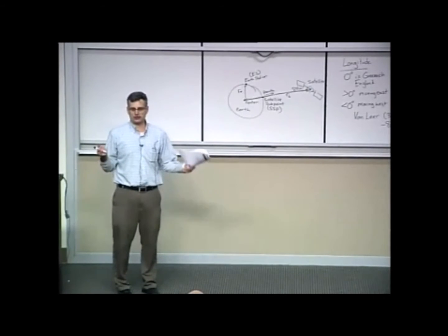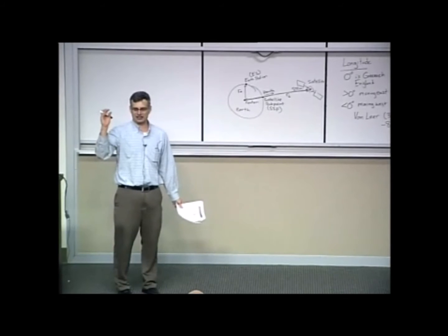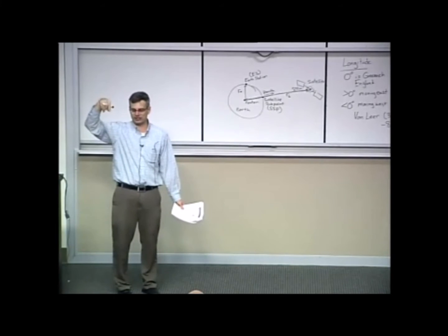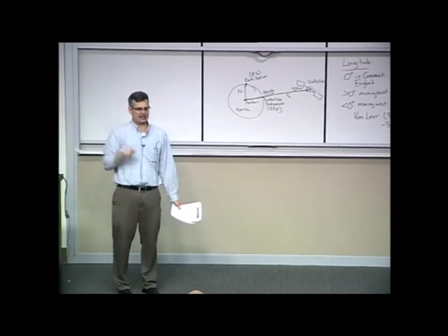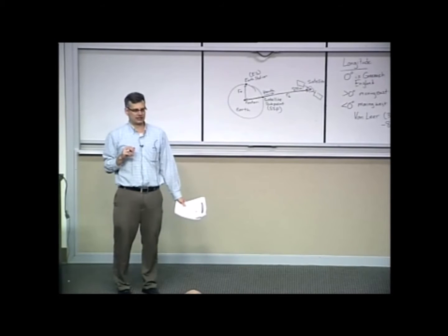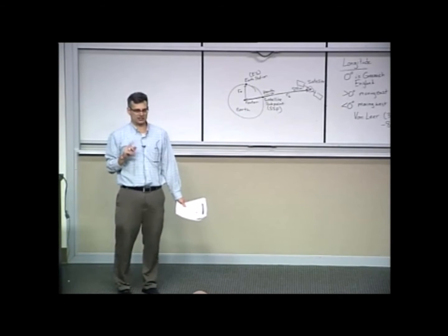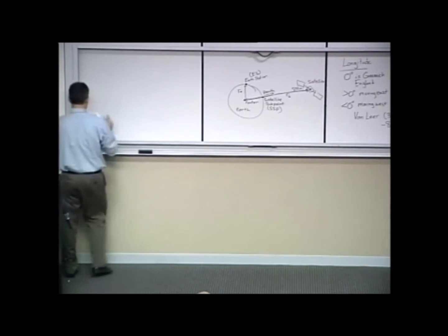And then we'll go into 3 dimensions where you actually have to use all the satellite subpoint and the Earth station latitudes and longitudes. That is a tricky problem. Take good notes because it's not in your book. I think the elevation calculation, ultimately what we're after is azimuth and elevation. They contain an elevation calculation, but I don't think they have the azimuth calculation included. And there's some nuances that they don't talk about either. So this may seem like simple geometry, but it actually gets very hairy. So pay attention. Here's our problem.